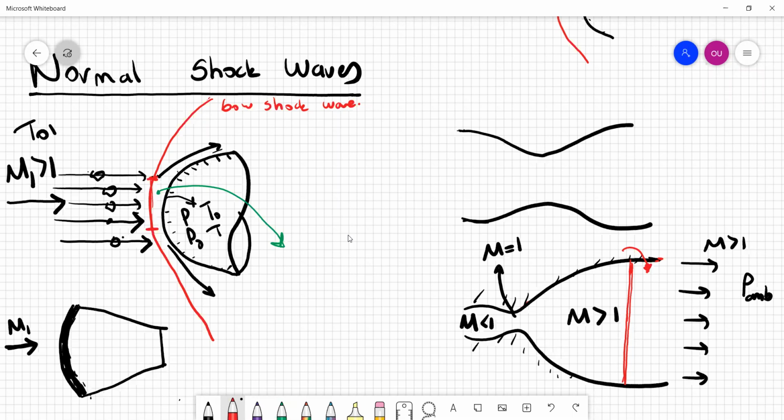We will discuss all these also in the aerodynamics 2 class, how to handle flow physics in an internal channel flow where we have geometry change like the nozzle shape, and we have these normal shock waves. We will see that. Okay, so these are some basically practical examples. And let me just mention, if you end up with a normal shock wave here, of course, it will be subsonic after a normal shock wave. Your exit velocity will drop very significantly, which means, I think you guys are also taking a propulsion class this semester. You may have already seen it, but maybe you will see it.